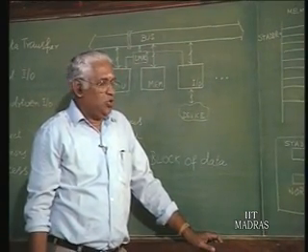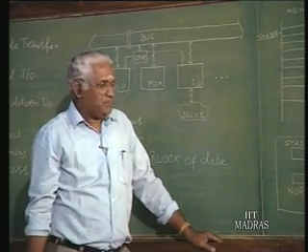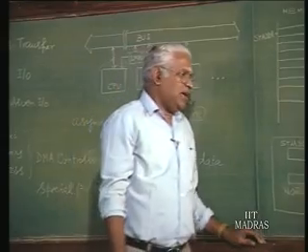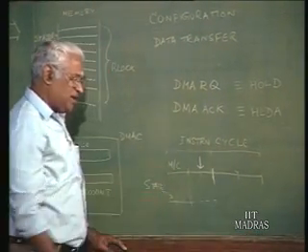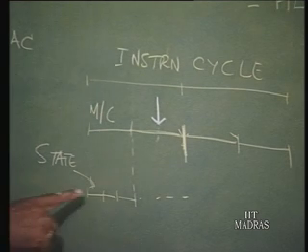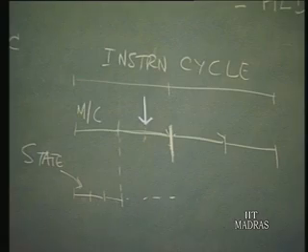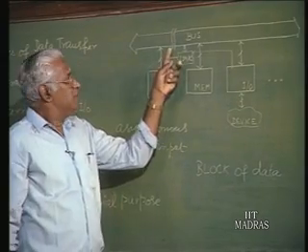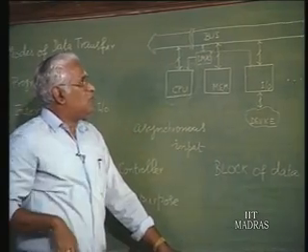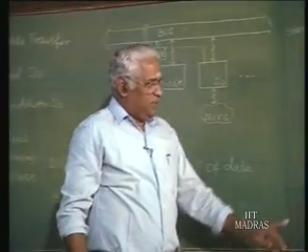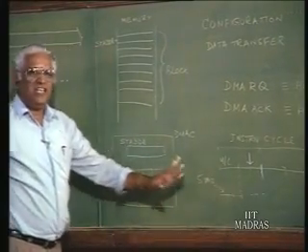Right. So, this way you can save some time, and sometimes it need not even be the end of the machine cycle. Why? Because we have seen earlier that not in all the states do we have bus activity. Suppose in a given machine cycle, the last state corresponds to incrementing a register.